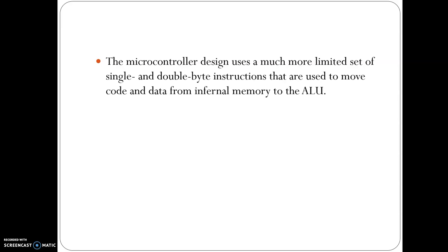Then the opcode of that particular instruction will be placed on the data bus, and that's how that instruction will reach the microprocessor. But in case of the microcontroller, the code, which is nothing but your program, and the data are present internally, and can be taken internally.